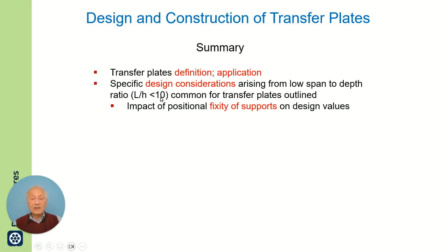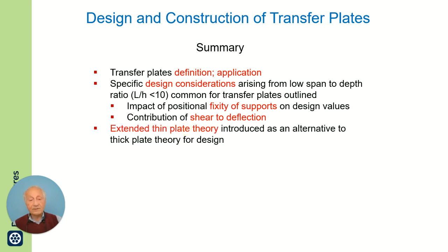I talked about the impact of positional fixity of supports. If the supports are fixed, you will also have some arching action which comes into the plate in addition to moment. I talked about shear deflection, that in transfer plates, shear deflection could be a design consideration.